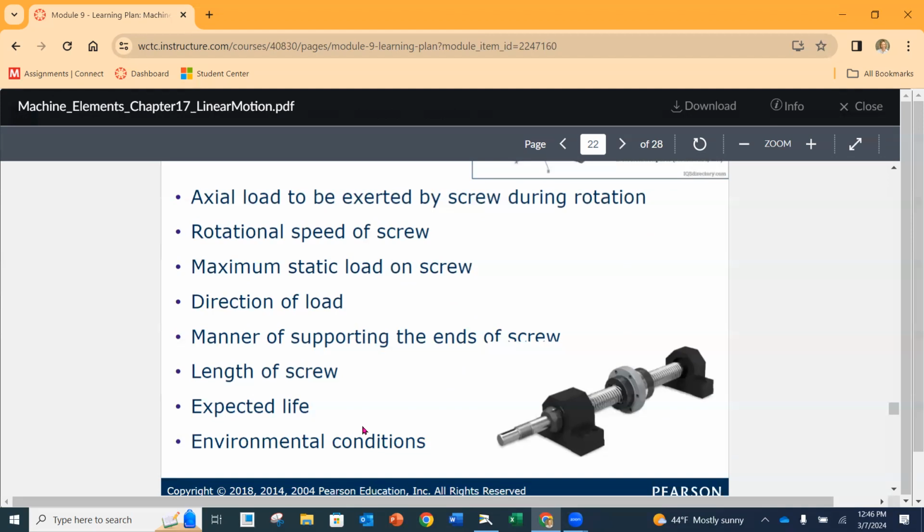that's all going to play into the type of screw that you get, whether it is a lead or a ball screw, but then also the materials that they're made out of. If we're in a food grade type of application, you're probably dealing with all stainless steel parts. But if you're in another application where there isn't as much corrosion, or you don't have to worry about that, then maybe steel or aluminum or whatever will be totally fine. So it's endless, and it just depends on the atmosphere.